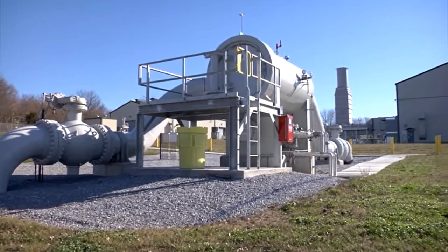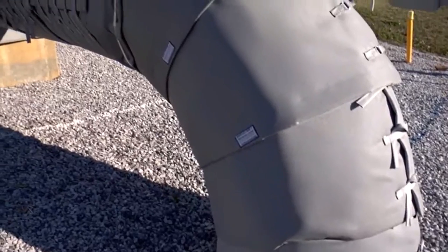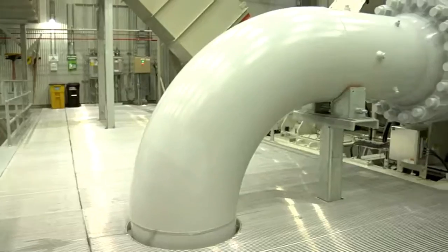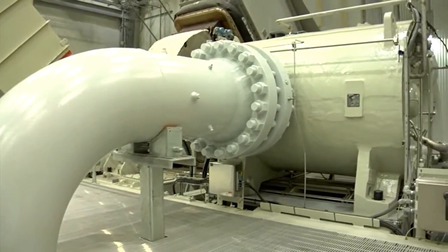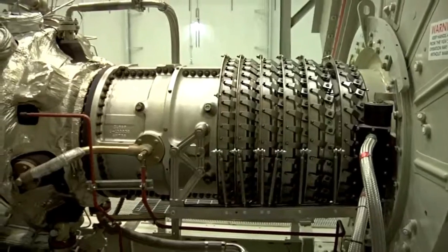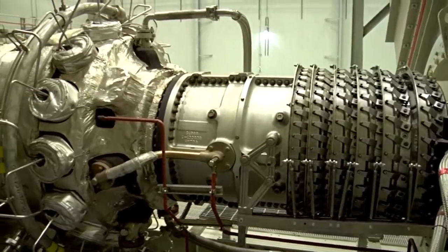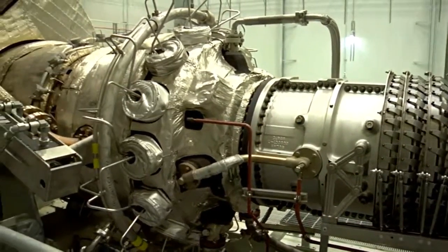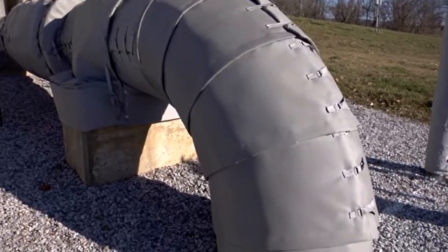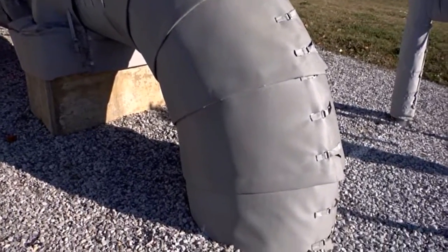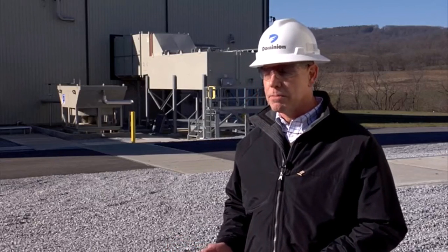It comes in through a suction line into the compressor station. It goes through a filter separator element that we have that takes out any impurities that might be in the gas. The compressor basically is driven by an engine, in this case a turbine. The gas goes into the compressor, it boosts the pressure when it's in the compressor. It goes back out into a discharge line from the station. It goes back into the main pipeline on a downstream side at a higher pressure.